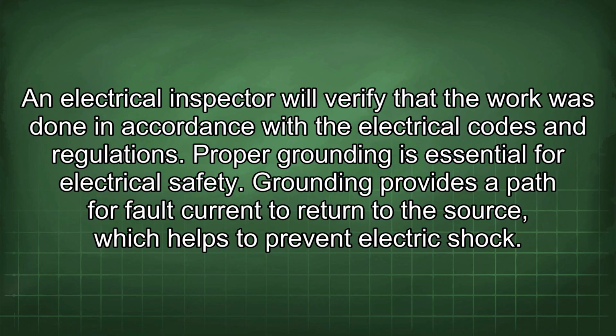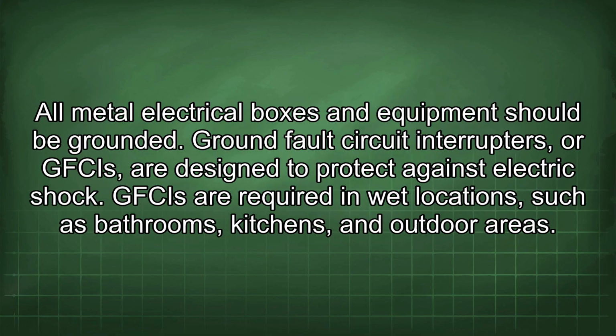Proper grounding is essential for electrical safety. Grounding provides a path for fault current to return to the source, which helps to prevent electric shock. All metal electrical boxes and equipment should be grounded.